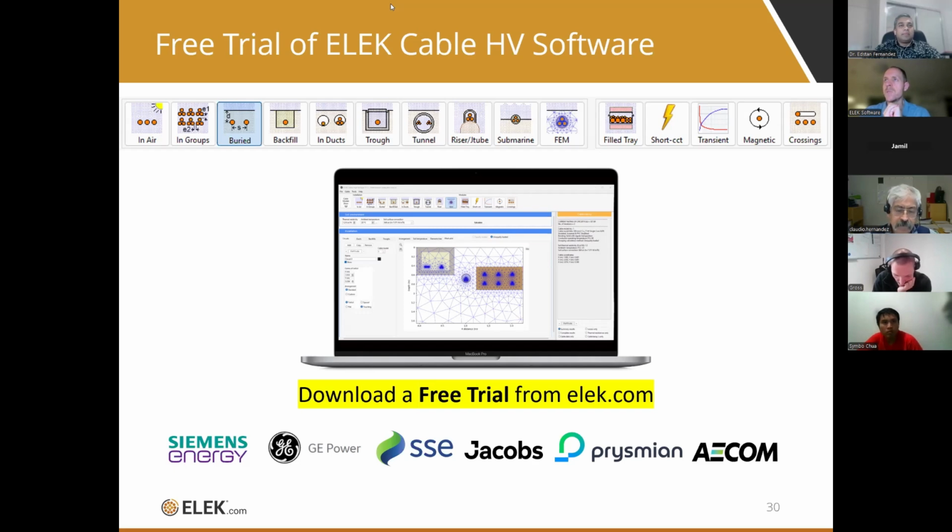If it's one cable system, then one section will dictate the ampacity of the entire system. What do you think? Yes, we could do sections, but I think the HDD section would be the limiting one compared to the cables in ducts. But as Jason told, you could have sections in our software, do each section, and then see which is the hottest point.